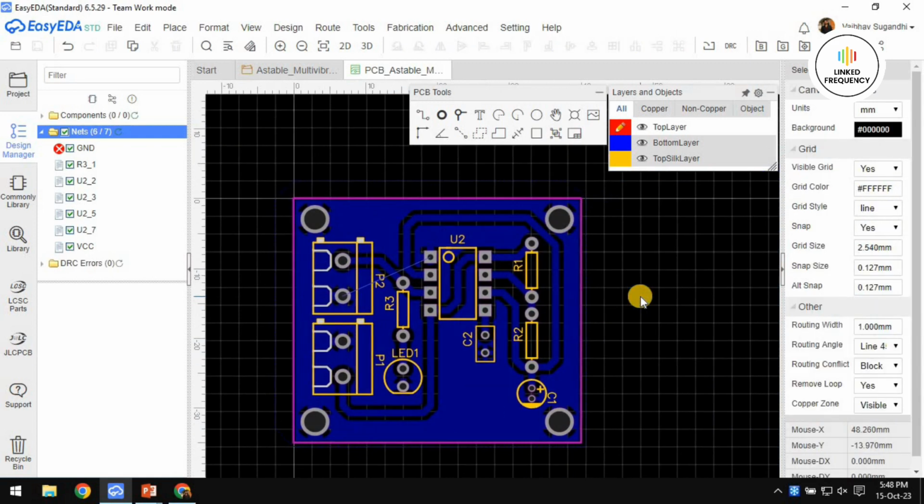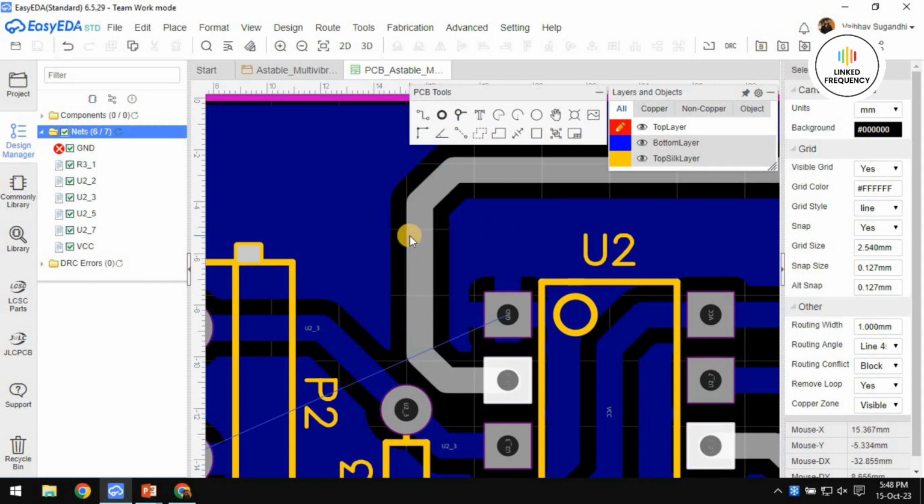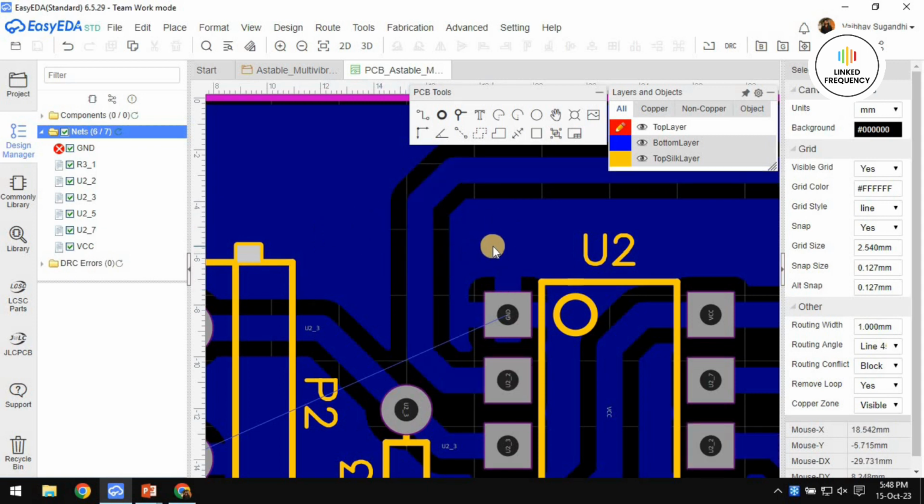Why? Because in this entire PCB, just because of this one particular path, if you are using a top copper, then your entire production price, or the PCB fabrication price, will be very costly, because you are using a top copper and a bottom copper just for one particular track. Instead of that, what we recommend is we use a jumper here. The jumper, in the sense, is just like giving two drill holes here, so that you can add a piece of wire from the top side after fabrication of the PCB, which is not good for mass production. Of course, it is suitable for prototyping only.